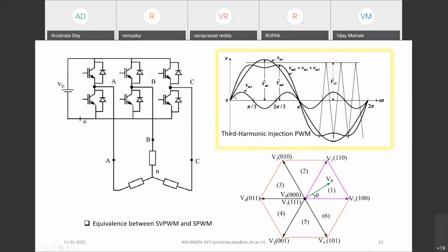And it should be like this, so that if you add the original signal and this third harmonic, your resultant waveform will be wavy in nature, and that will pull down the previous original peak to a lower value. The two maximum heights you are getting will never cross this particular line. So you never enter into overmodulation.